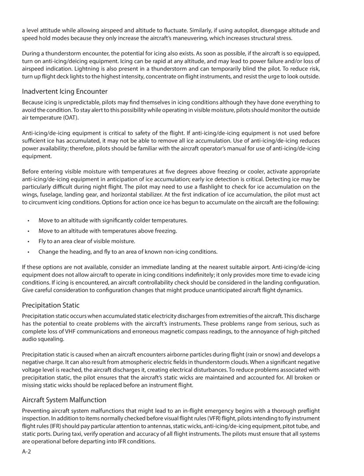Anti-icing/de-icing equipment does not allow aircraft to operate in icing conditions indefinitely, it only provides more time to evade icing conditions. If icing is encountered, an aircraft controllability check should be considered in the landing configuration. Give careful consideration to configuration changes that might produce unanticipated aircraft flight dynamics.